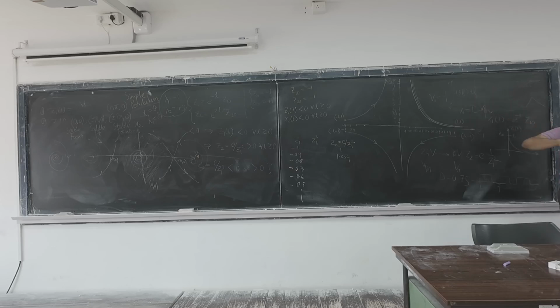Ultimately your voltage would be the arithmetic average of this AC signal, because whenever it is a switching circuit, you cannot expect perfect DC output. Of course it would be pulsating, and then we have to consider the average. The point is that in power electronic converters, you have two stable equilibrium points, one corresponding to T on and another corresponding to T off, and we are forcing the system to jump between these two stable operating points, because of which you will get the averaging.